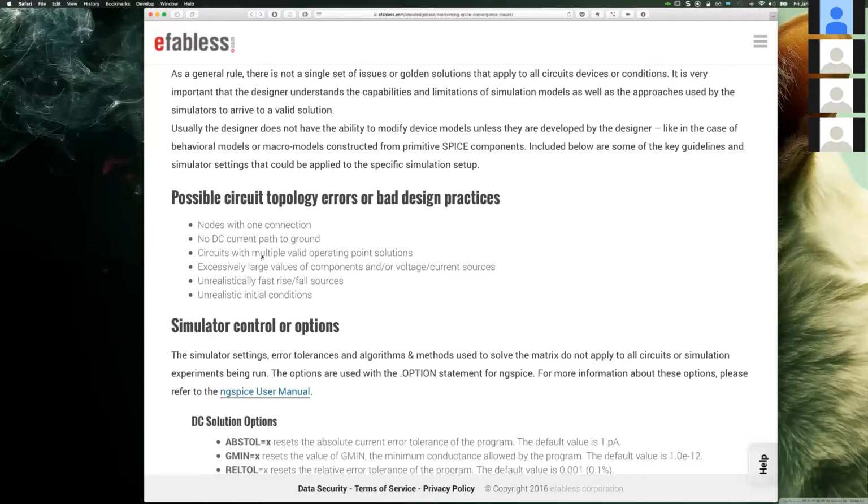It could be valid mathematically and valid physically. The danger is that you will assume the circuit works in simulation, and in the lab it is either completely dead because it didn't operate, since one of the valid operating points would be the zero mode, or it functions at a different voltage or operating point that actually sticks there.